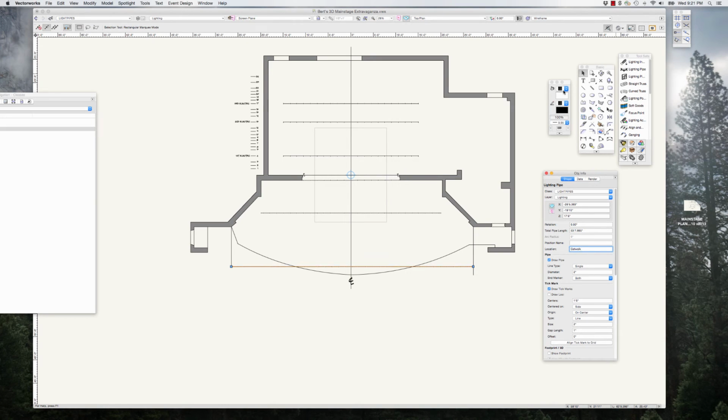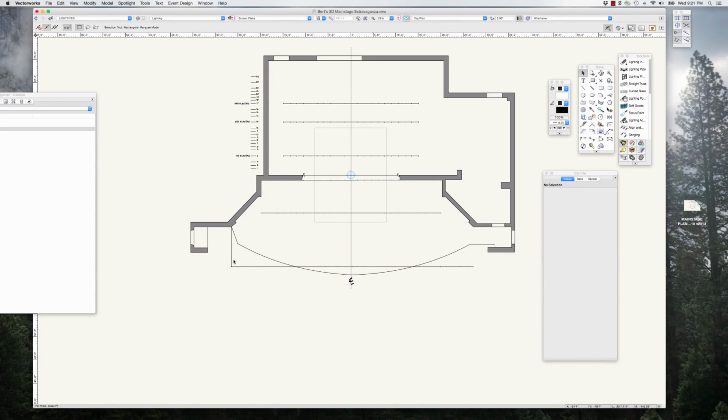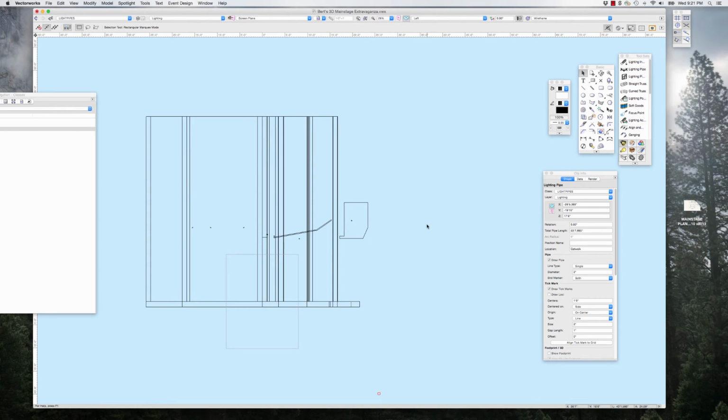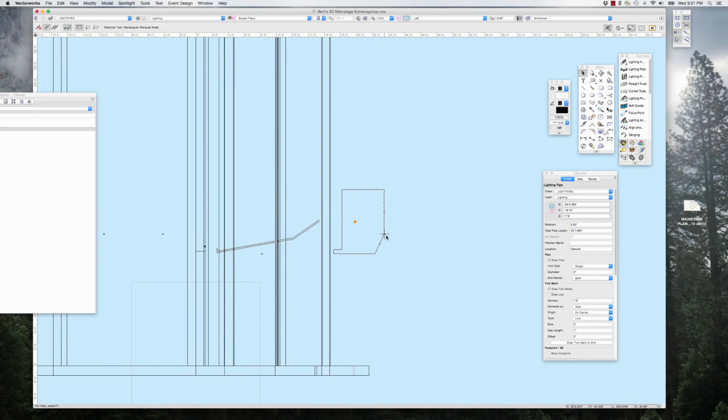And then exactly where that goes upstage, downstage, I have to look at the section view, the side view again. So I'm going to hit 4. Yeah, that's way too far downstage. It's more like right, well, depending on which pipe I'm drawing, if it's the top pipe, it's actually back here. If it's the far pipe, it's more like right there. I'm going to put it in a position that doesn't really exist and put it right there because it's going to be more useful for model lighting if it's there.